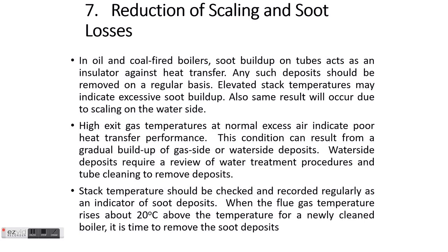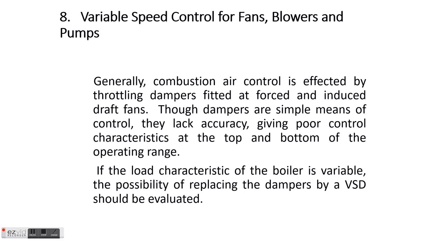High exit gas temperatures at normal excess air indicate poor heat transfer performance. This condition can result from a gradual buildup of gas side or water side deposits. Water side deposits require a review of water treatment procedures and tube cleaning to remove deposits. Stack temperatures should be checked and recorded regularly as an indicator of soot deposits. When the flue gas temperature rises about 20°C above the temperature for a newly cleaned boiler, it is time to remove the soot deposits.